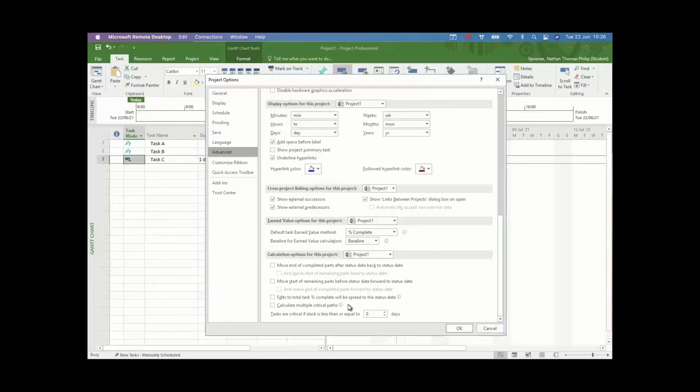Usually you'll only have one critical path going through your project, whereas this button allows you to visualize every single critical path you've got. This is important because it enables you to consider the additional resources which should be applied to those specific activities to ensure they are completed on time. This enables your project to be completed by the estimated duration, unless something else happens.